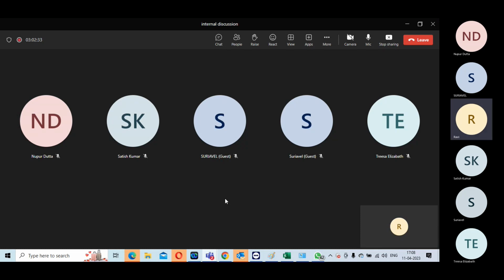In that area, there are paths where you have positive slack. Where there is positive slack, there you downsize. Don't touch the critical path; you remove the buffer without impacting the slack. So you have to manually create space, in case you want to add a buffer. How you create space is like this.